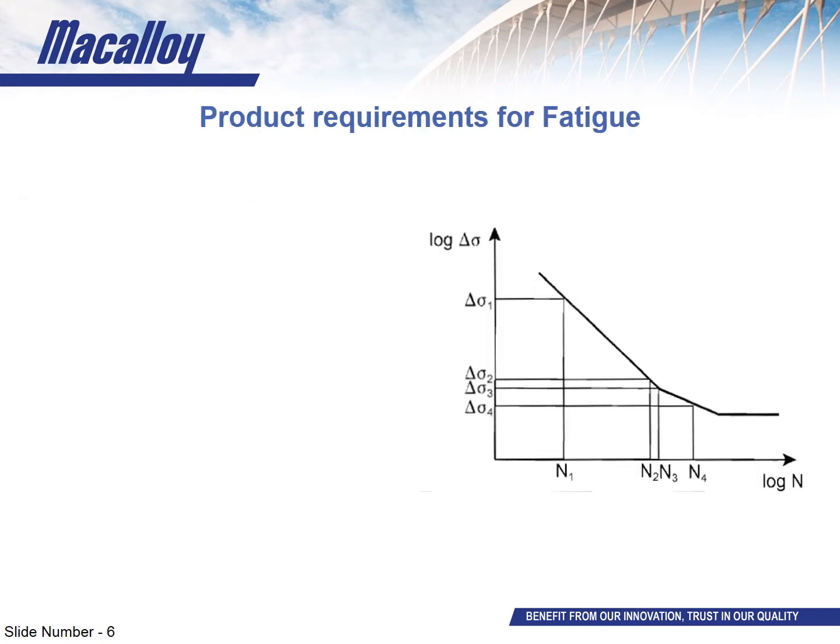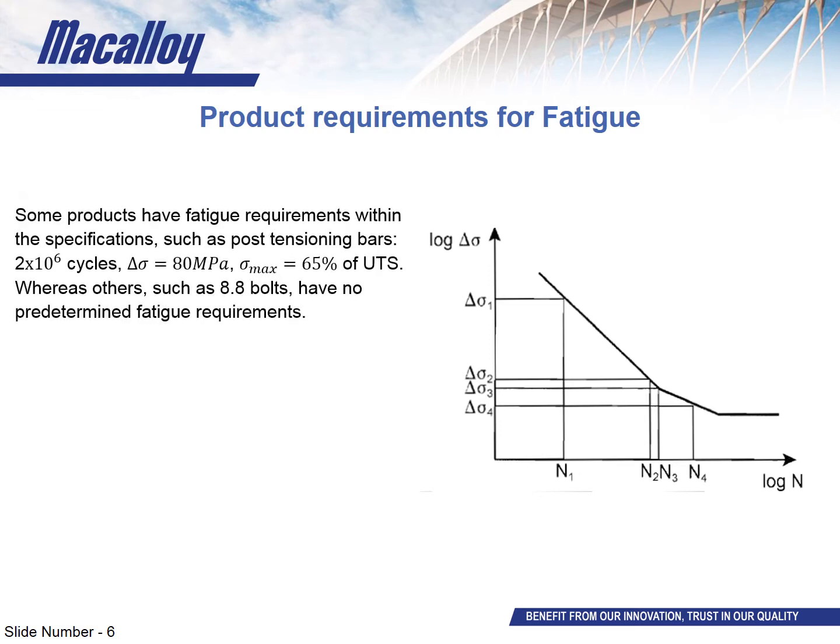Now, unlike the last webinar, when I say tension rod, I'm not referring to architecturally exposed structural steel in this presentation. I'm using it just as a general term, meaning steel bars that are used in tension. Requirements for a specific product, such as a post-tensioning bar or marine tie bar, are often outlined in the related standards. So for the post-tensioning bar, that would be the European assessment document related to it, and then for the marine tie bars, that would be EN 1993 Part 5.